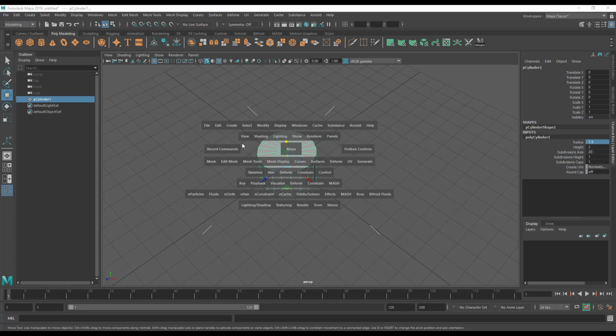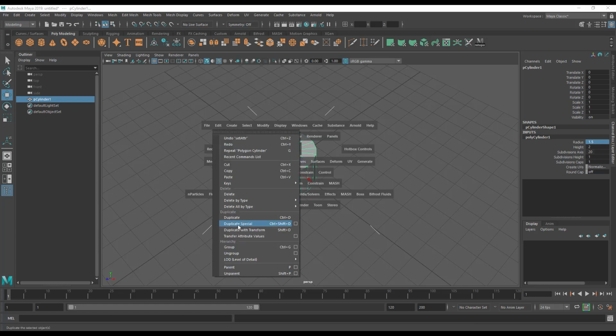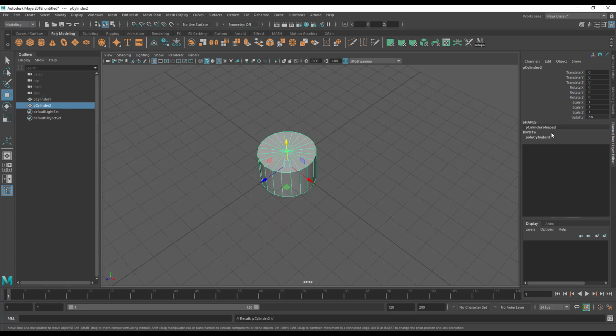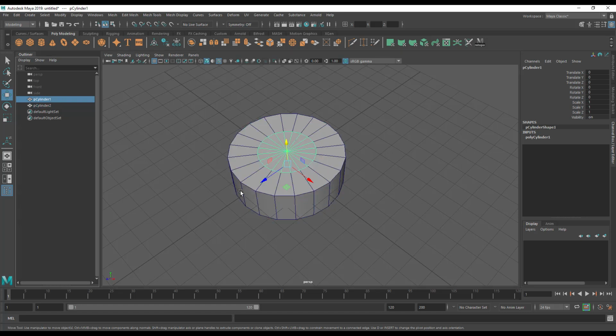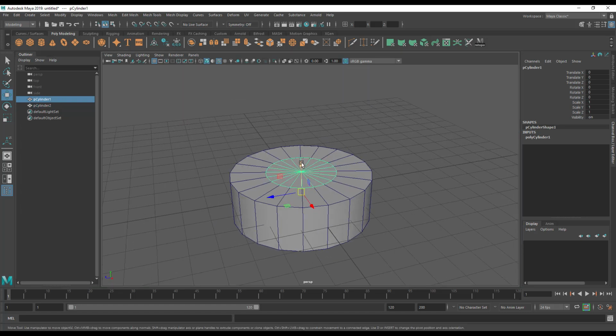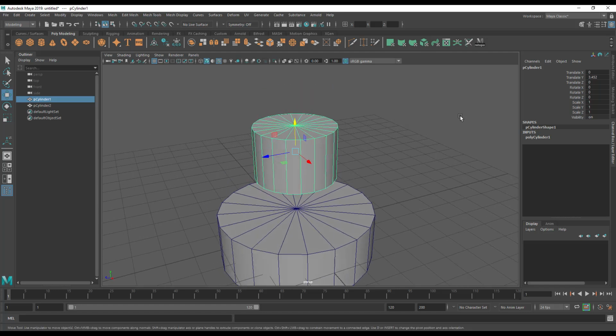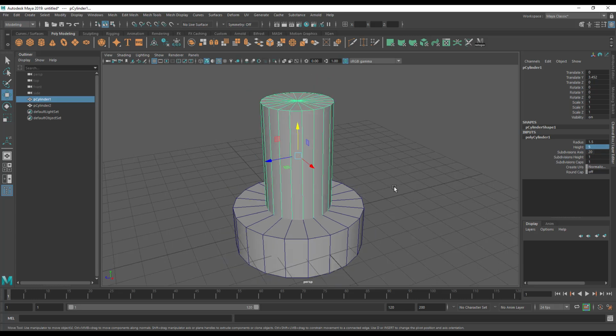I'll then duplicate this special, so edit, duplicate special, and I duplicate special to preserve the input connection. I can then come under here and say make it twice as large. I can then use the original cylinder as a drill bit, so to speak, to just drill a hole through this, which I'll show you in a second. So in this case I would want to make this a bit longer because it has to completely bisect the object it's drilling through. I'll just make that 5.